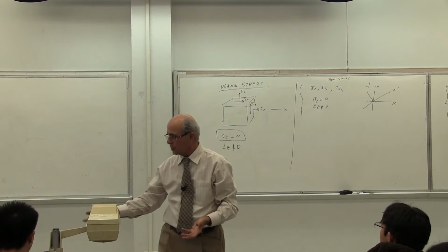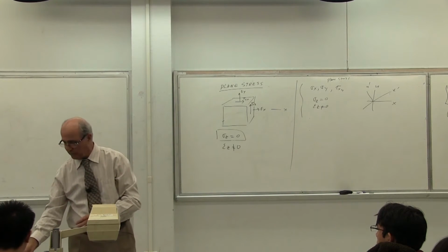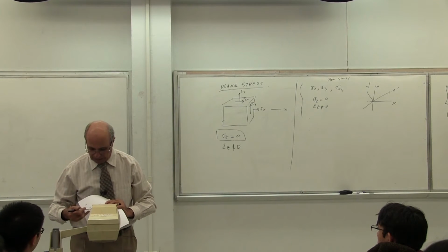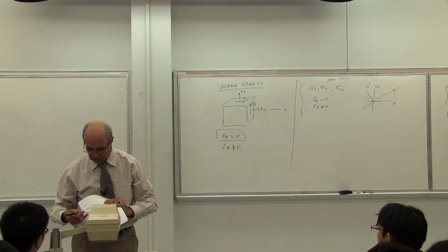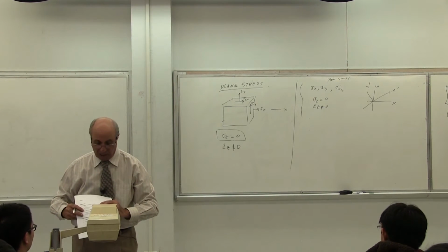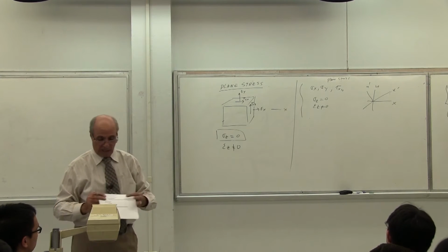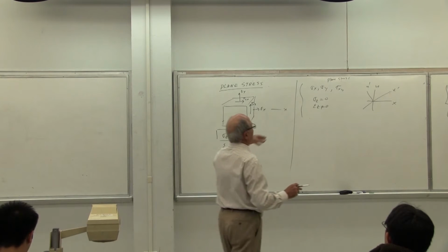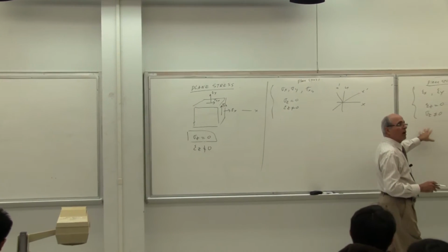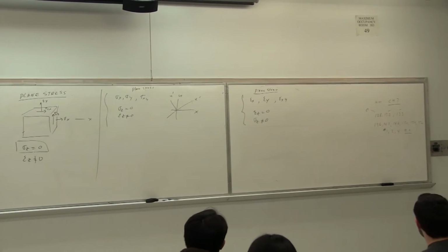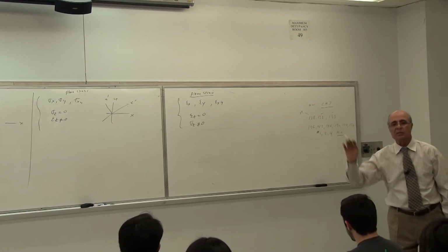That's what I put there in the background, first page 1. Okay. So that is epsilon x, epsilon y, epsilon z. Then this is gamma xy, which we already gave the rotation. Then we said the state of stress. That's the state of stress. Then we said Mohr circle. Yes or no? Correct? This is plane stress. Now I'm changing it to plane strain. Why? Because in real life, you are going to measure epsilon x, epsilon y, and the gamma, and go backward. Is that correct or not?